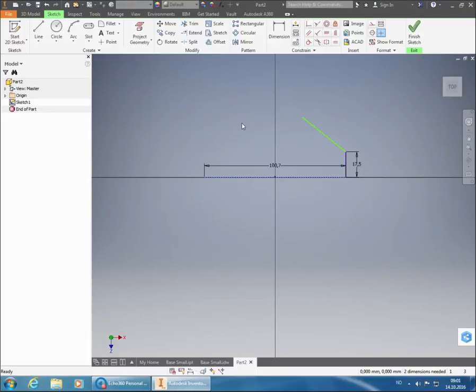And what we want to do now is to actually create the curve up top here. So we're just going to create a full circle, and we're going to place it where it's supposed to be. Because then we can do this line, and we can connect it to the circle and make it become tangent with the circle. So first off, I'm just going to place a circle. And I'm going to set it to the correct diameter. Now the radius up top here is going to be 17.5. So then I put in 17.5 and I multiply with 2 to get the diameter.